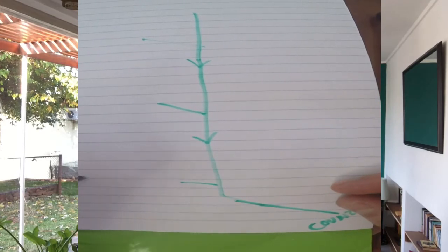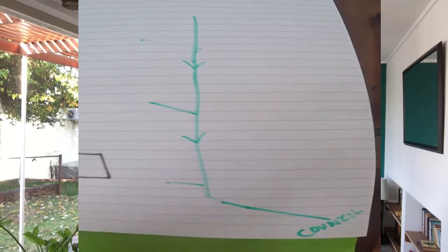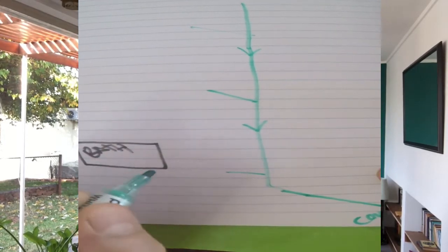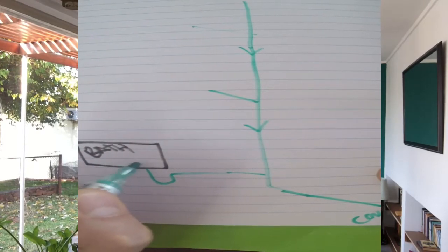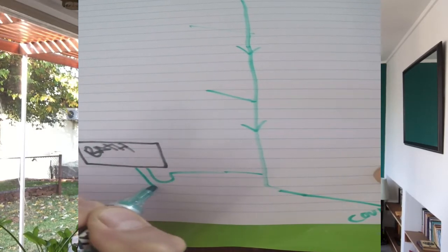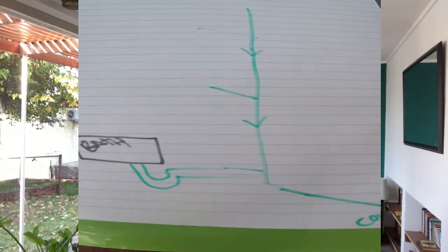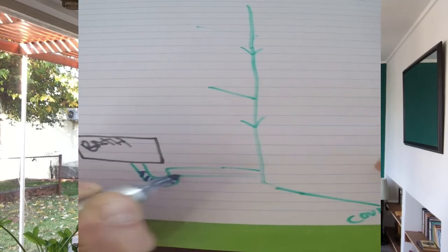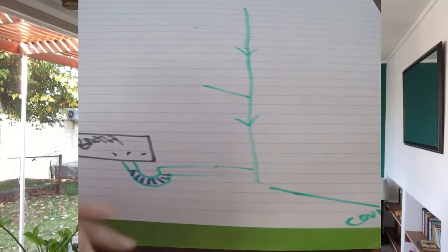So I run my bath and I want to drain it. So I pull the plug on my bath, and what we put in there is a trap. We put a trap so that when I pull the plug, this water goes down, but when this is standing empty, this trap stays filled with water. And then I do not smell the pipe work.